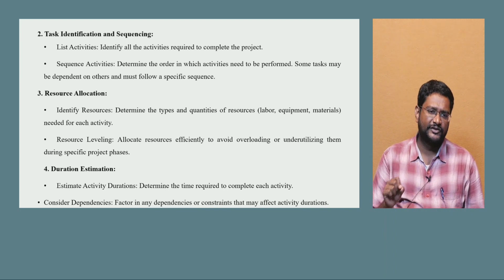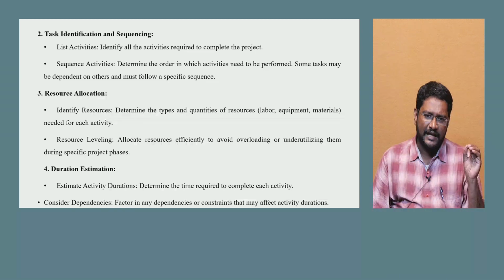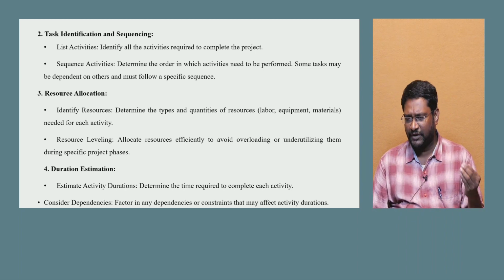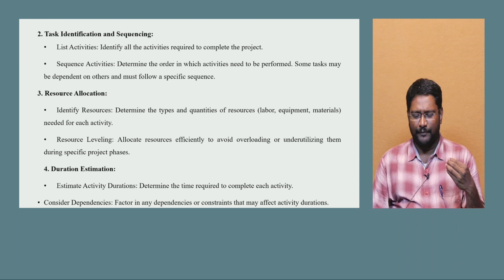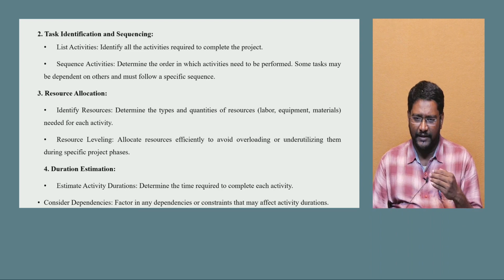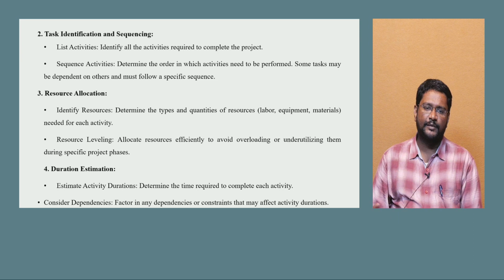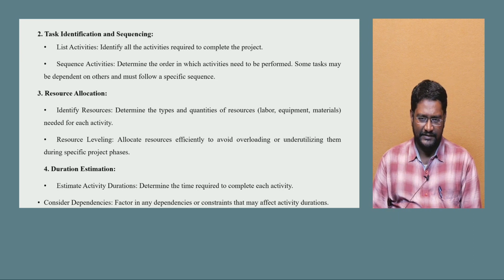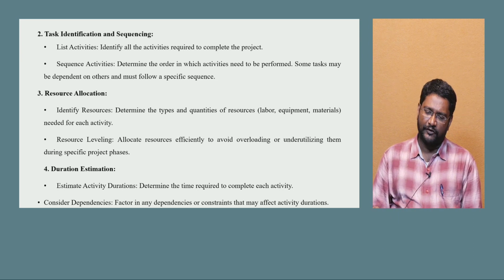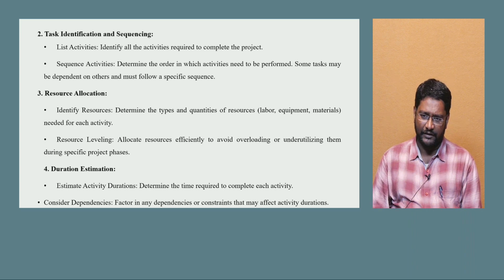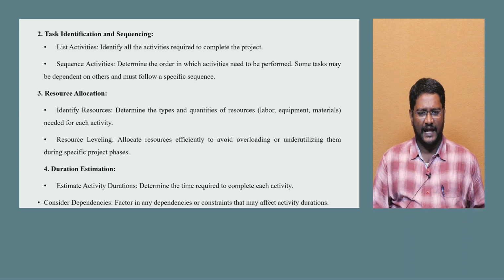Okay, next is resource allocation. For each task we have to allocate resources, maybe labor, material or equipment. Identifying the resources: first of all determine all the types and quantities of resources, maybe number of labor, quantity of equipment and material needed for each activity. Then resource leveling: allocate resources efficiently to avoid overloading or underutilizing them during the specific project.